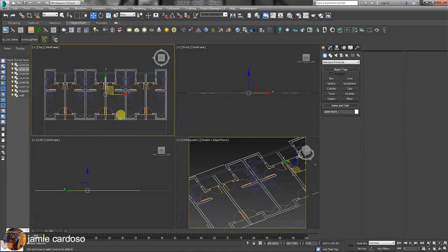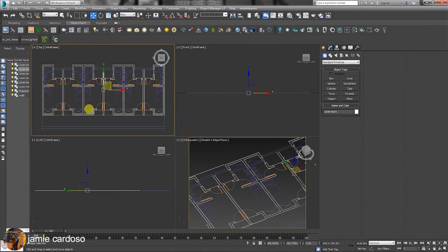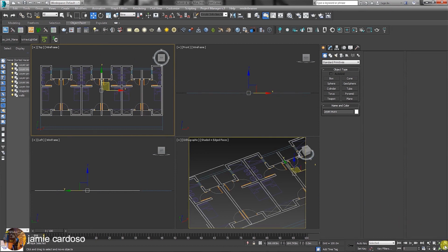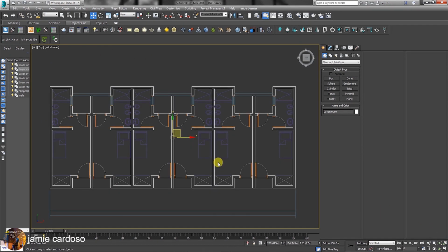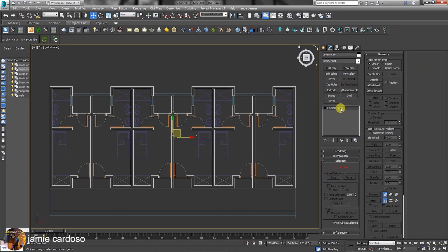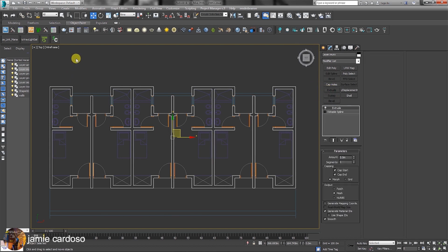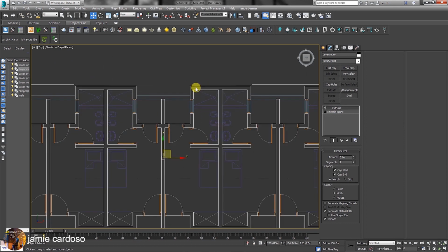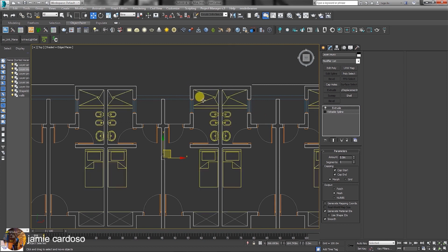This is another example for users in the ArchViz industry, whereby you'd normally import a DWG file into 3ds Max and trace over the splines. Users trace over the splines because they're often overlapping and can't be extruded correctly. As an example, if you were to extrude these walls and turn the viewport to shaded, you'd quickly realize that the inside walls are not shaded. The spline edges have been extruded but not inside. This often happens when vertices are not welded.